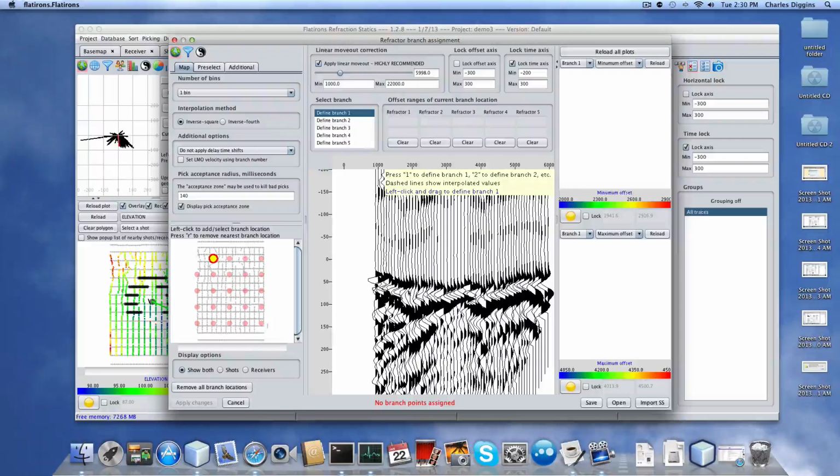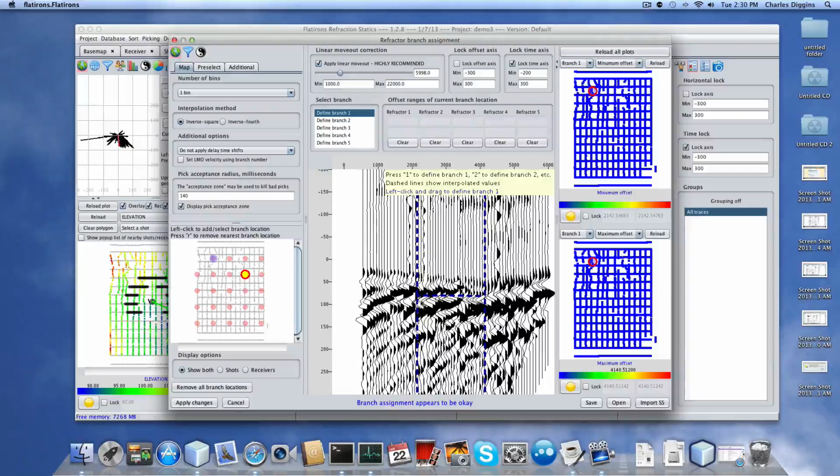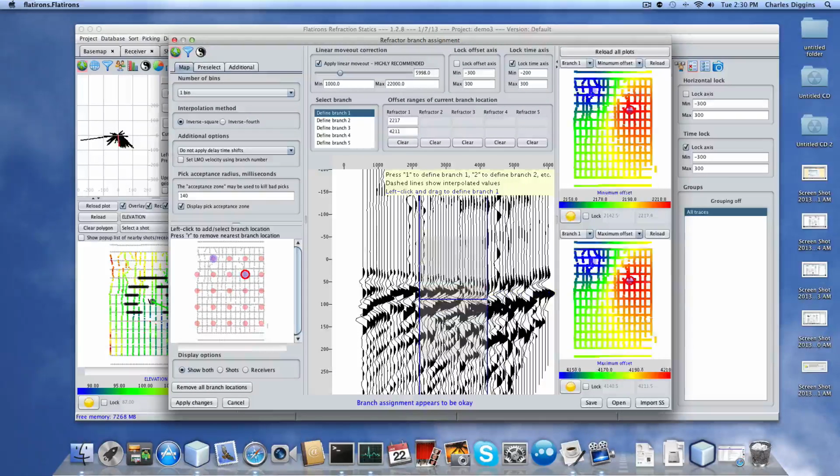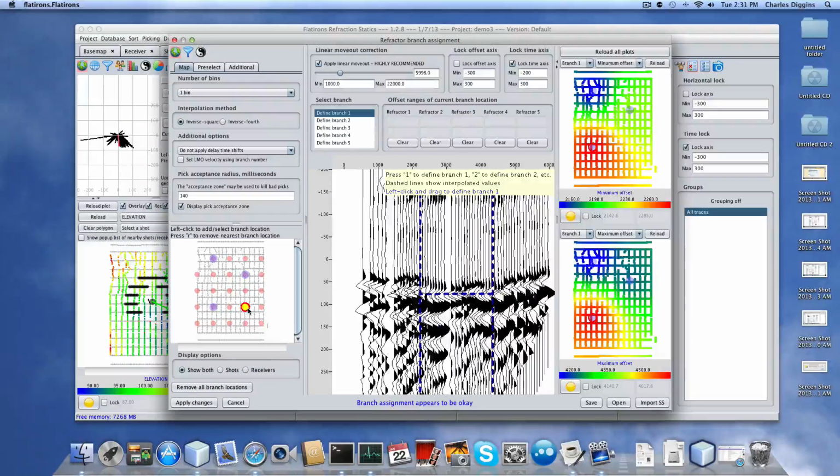As you can see, we have a shallow or a slow velocity. Let me redo that whole thing here. 5,500 or so, 54. About close to 6,000 feet per second, and another one that's closer to 6,700 or 6,800 feet per second. So again, I'm going to go after this refractor here in the middle, right here, set it here, and then set it down here.